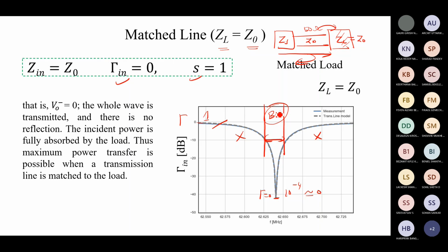This bandwidth is actually derived out of the reflection coefficient, which is derived out of the impedance. That is why this bandwidth is often referred to as impedance bandwidth. This is the interesting advantage of a system. Assume that I have a transmitter and a receiver, and both are tuned for a particular frequency. We call that the operating frequency f0, and the transmission line is matched in such a way that it is operating at this particular frequency f0. So a secure transmission will come.